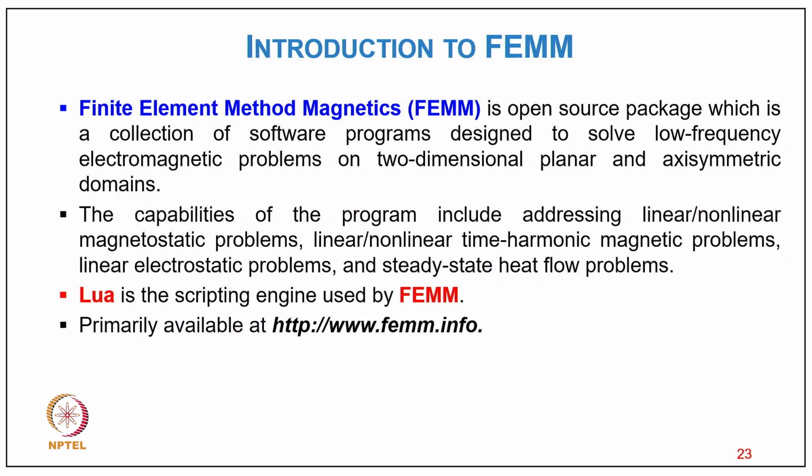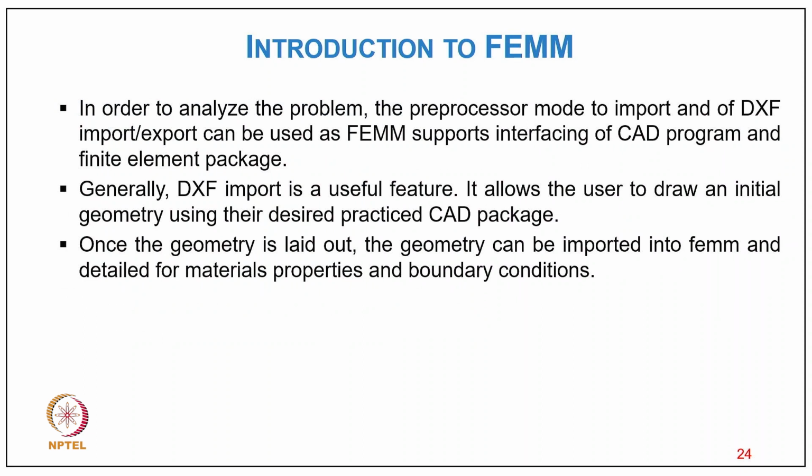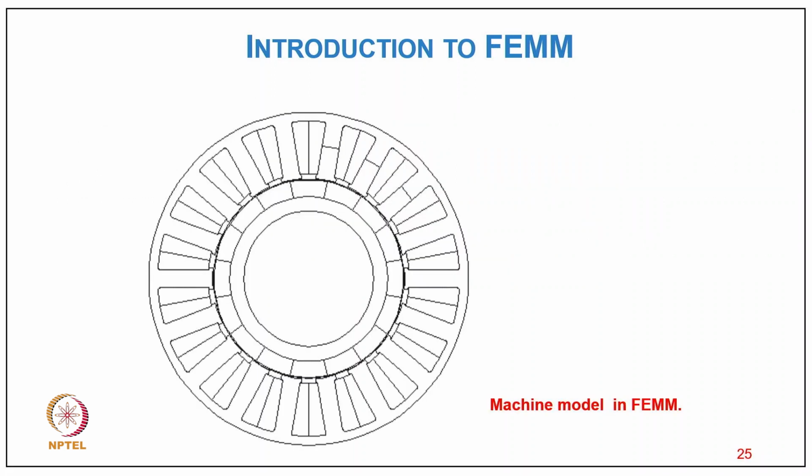Lua is the script engine used in Finite Element Method Magnetics, and is typically available at the website. In order to analyze the problem, the preprocessor mode and the DXF import and export can be used, as FEMM supports interfacing of CAD programs and the finite element package. Generally, DXF import is a useful feature that allows the user to draw an initial geometry using their desired practical CAD package. Once the geometry is laid out, it can be imported into FEMM and the details of the material properties and boundary conditions added. So you can see typically how the machine model looks in FEMM.